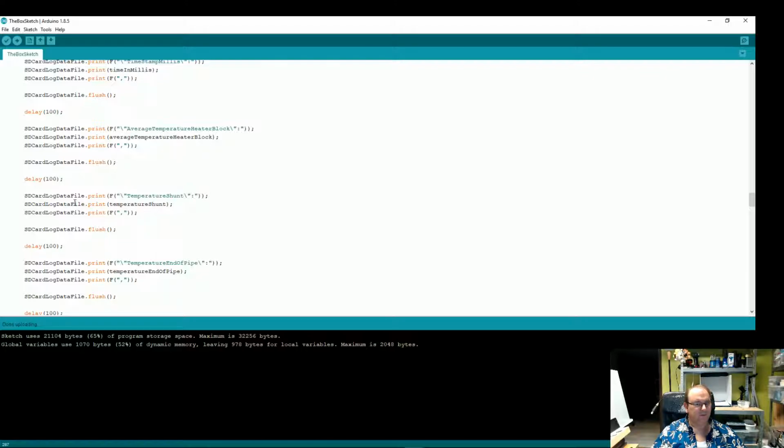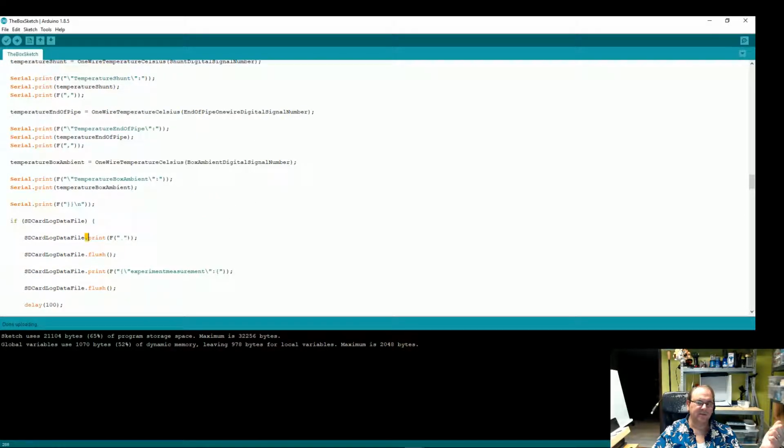Yeah, so that was pin 10 can't be used. I had to add this phantom print statement at the beginning, and then I was using this flush. Is there anything else? No, and then it seems to work with all SD cards: the old one, the medium age SD card, and the big new one. All of them work. Plus the card info works. If I run the separate sketch for card info, that works every time. I haven't noticed that it breaks down anywhere.